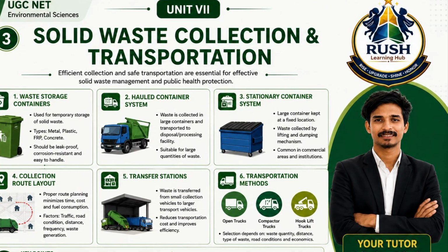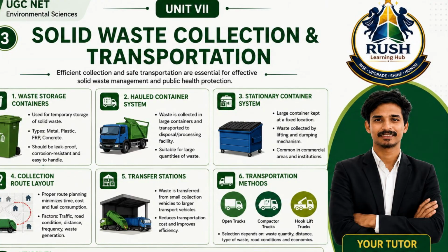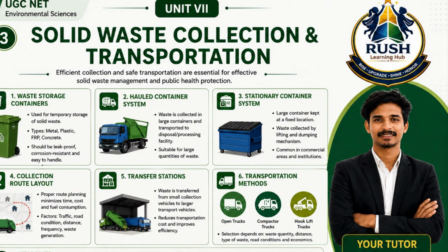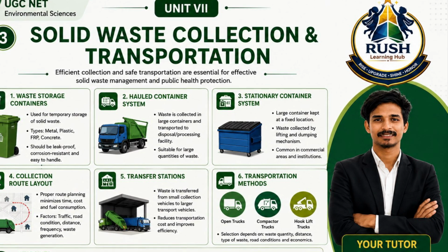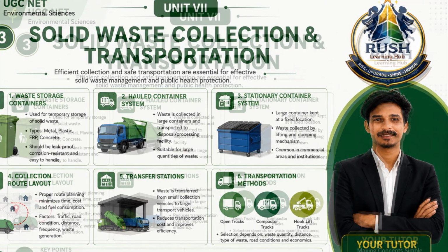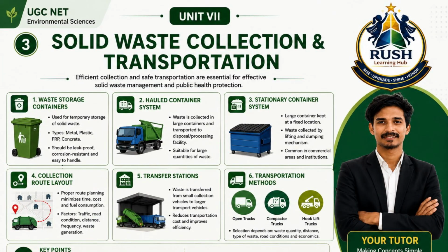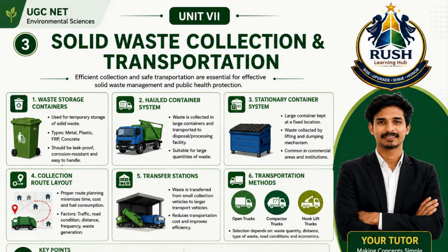container. This system is generally used where large quantities of waste are generated, such as industries, construction sites, markets, and commercial complexes. The main advantages of the hauled container system are efficient handling of large waste volumes, fewer collection trips, and reduced manual handling. However, the disadvantages include higher transportation costs and the requirement for specialized vehicles.